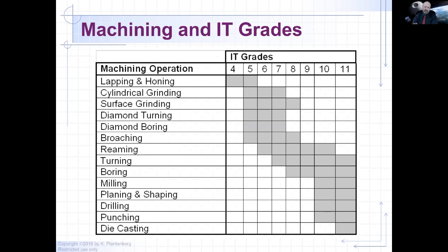That's where you make a mold of something, usually with sand. You can do sand casting. There's also other kinds of plastic casting and whatnot, but sand is typically done, and then you pour molten metal into the mold, and then you end up with a part once it cools down. That's going to be real rough, the tolerancing for it.